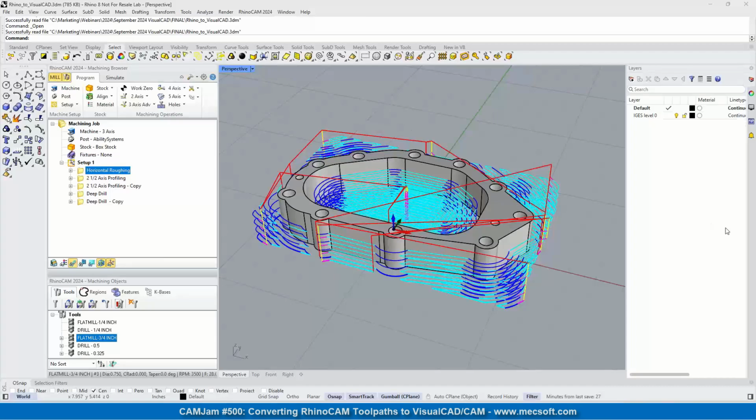Sure. So yeah, what we see is VisualCAD is a shop floor system. So we're targeting VisualCAD to more of the simpler geometry machining processes. So when I say that, it's typically DXF files, users are bringing in DXF files. Maybe they're running a laser cutter, 2D machining, flame cutting, things of that sort. It's ideally suited for something like that.